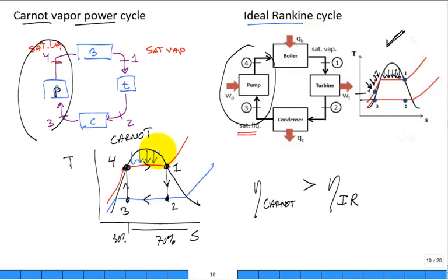It starts boiling right away because it's already saturated liquid. If I add a little heat, I'm going to get some vapor right away. What about the Rankine? It was cold liquid. I added heat, it just made it warmer liquid, warmer liquid, warmer liquid. It had to crawl from about 40 degrees C in the calculations that we just did up to around 390 degrees C before it started boiling. You see that?